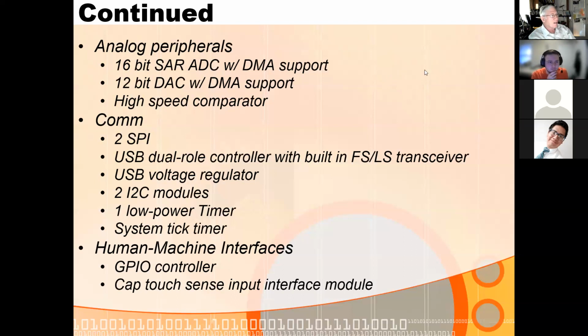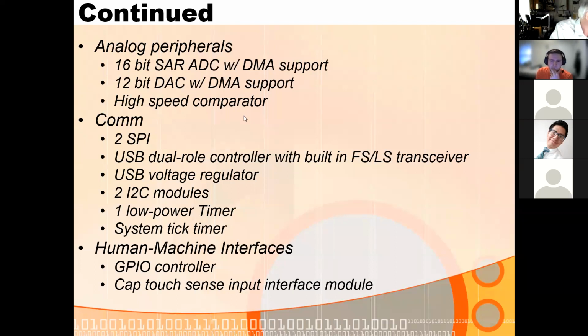It's spec'd at 20 milliseconds, but we're cheating on that already, running it about twice as fast, and still we have practically forever to sample the touch panel as many times as we want. So we're averaging 32 samples in the X and 32 samples in the Y direction to take some of the noise out of the data, which is really nice.